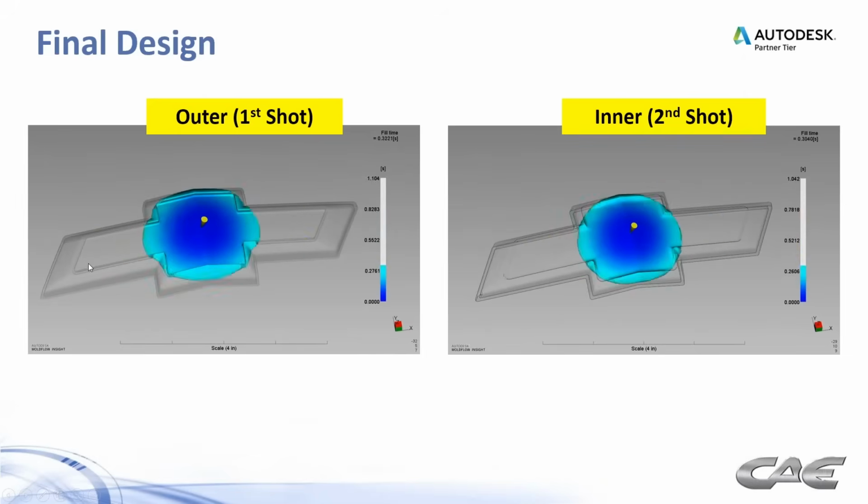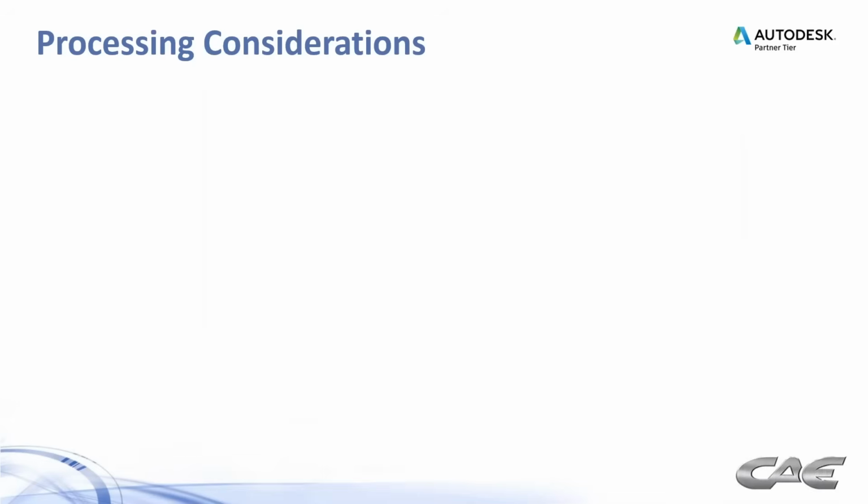create a knit line, but it evens itself out pretty well. And then we actually started inducing a little bit more of that flow race tracking on the second shot because we thickened that area up, but not to the point where it was going to cause any concern for a knit line. So that's the what if that you can do with part design when it comes to two-shot, and you want to see which shot you need to thicken, which you need to thin, and what, so to speak, can you get away with on that. So there's some part design considerations.